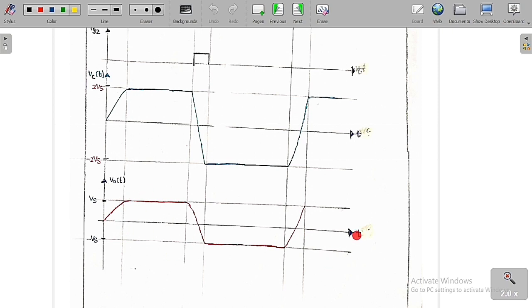The same graph is going to repeat periodically. So this is the way that you need to trigger T1 and T2. Therefore you are going to get the output voltage like an AC wave. So the input is a DC wave, but the output you are going to get is an AC wave. That is the function of the inverter. The basic function of an inverter is to convert a fixed DC voltage into AC voltage of variable frequency.